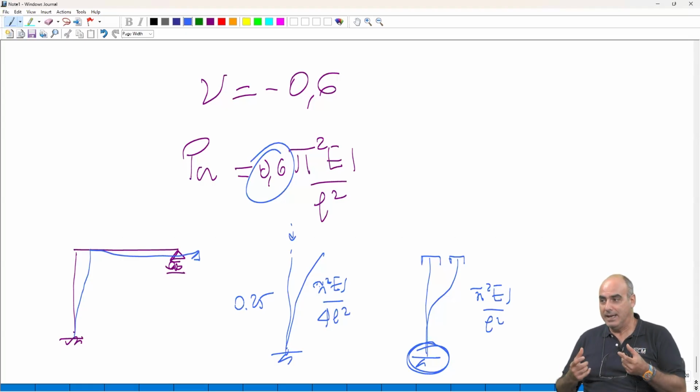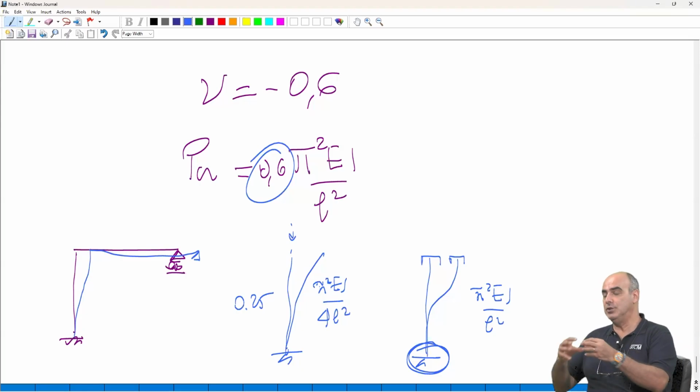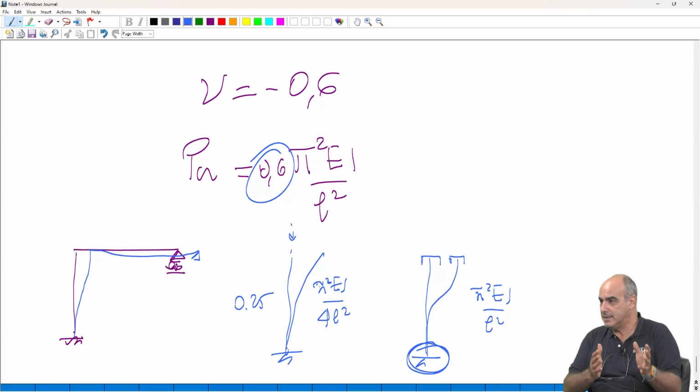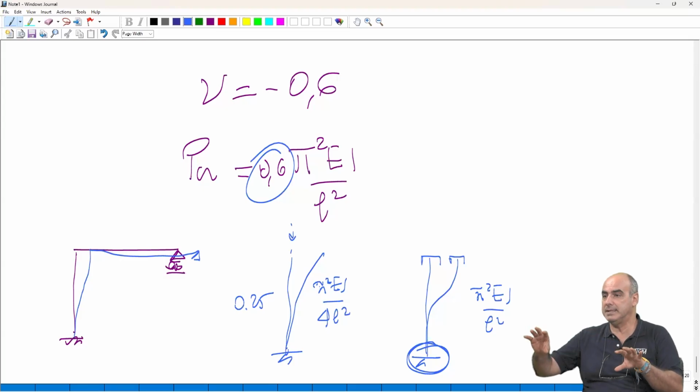So you will like the joining devices to break because they are ductile, they can deform, instead of the elements breaking. But also for another reason: if the failure is in the joining elements, it's easy, for example after an earthquake or after a major windstorm, to go there and replace these steel devices because the elements are sound.